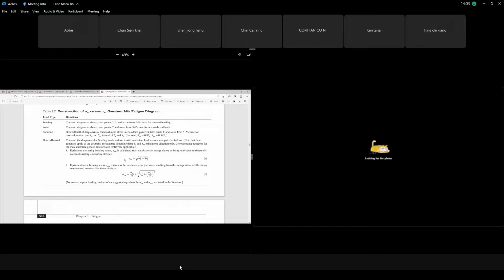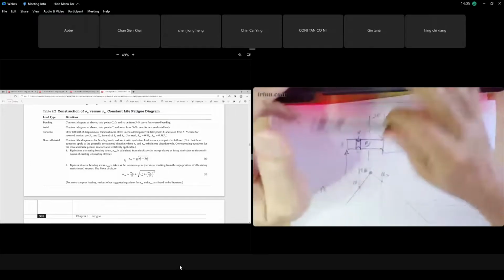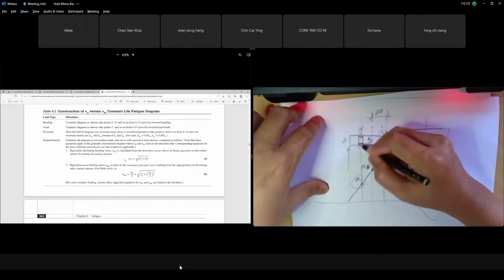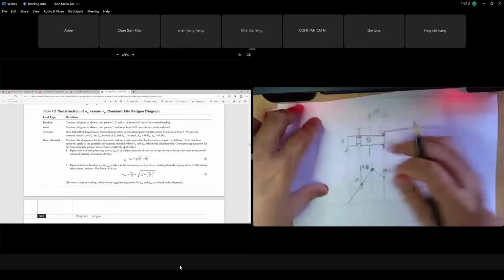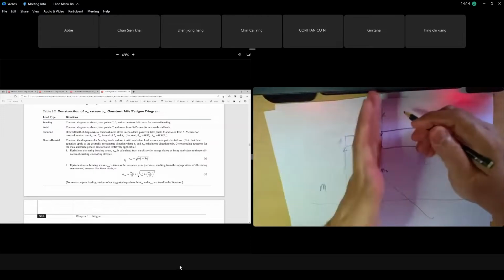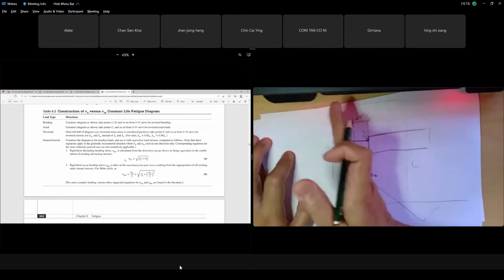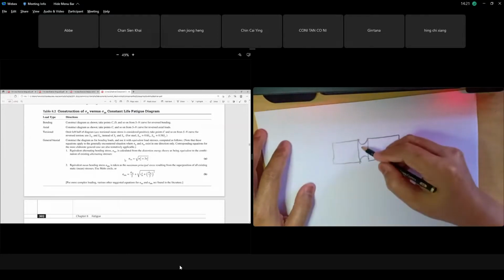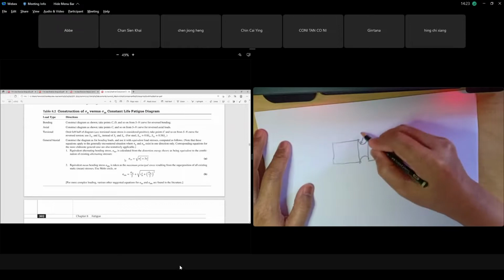Okay. The groove, for you to mount the washer, like a snap fit ring, is to prevent the pulley from sliding to the left. And this one will be locked by the shoulder here, right? So this kind of shaft, if you have a groove here, you have a small radius here.